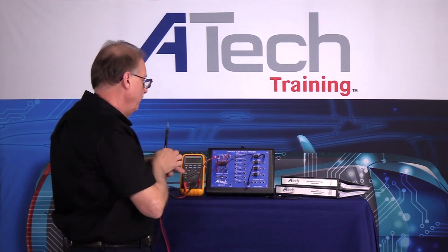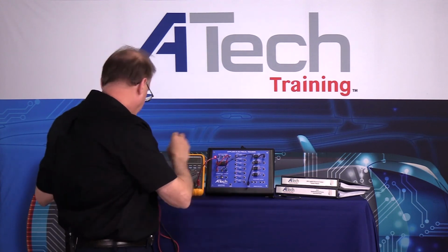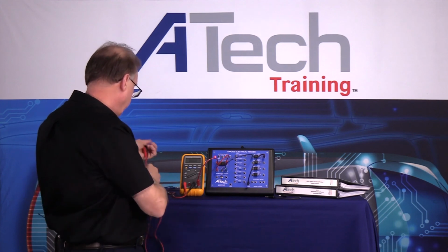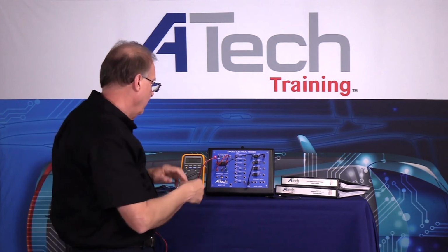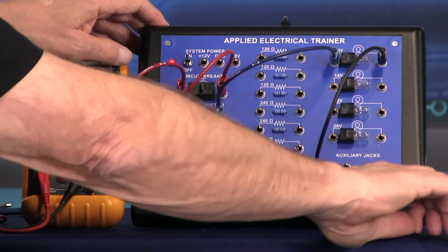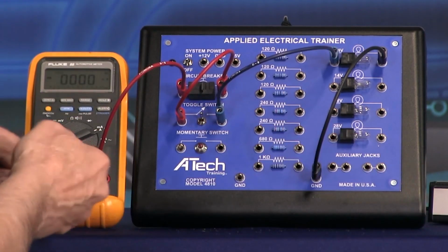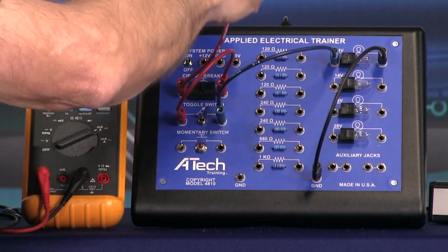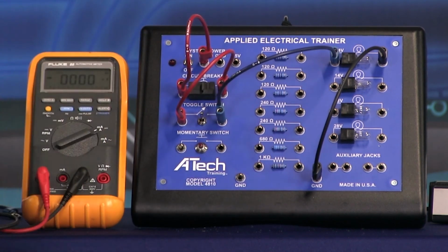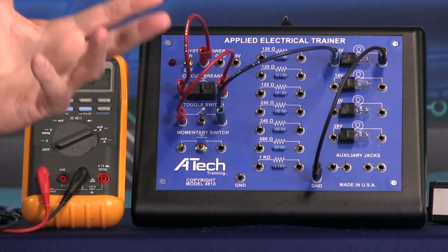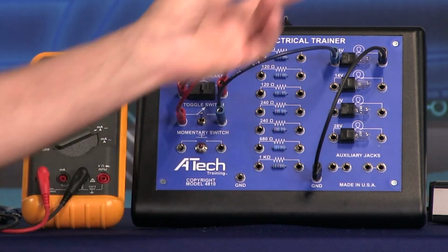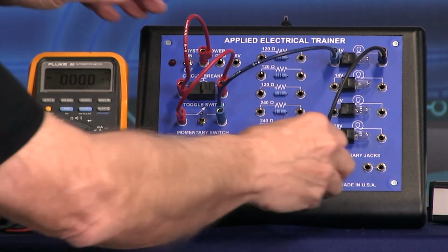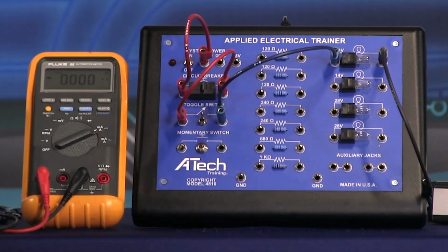So where would I go next? Where would I go next on this circuit? We'll turn it back off again. So we have the circuit there, and I've lost my red lead for a second. We'll just use a different one. No, it isn't. It's right here. All right. So I got my circuit breaker up here. So where else could I check? I could check on any part of the circuit. I should have the same amperage. So I'm going to go to the ground side.